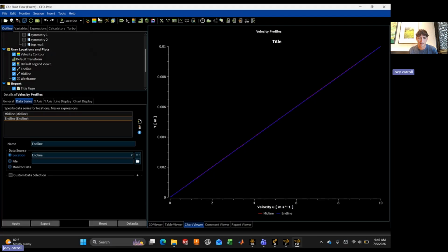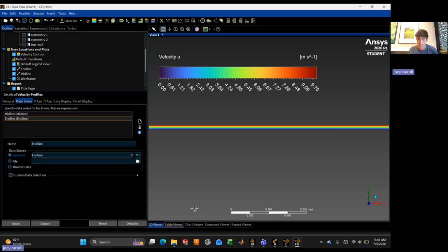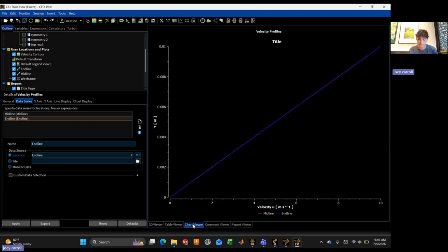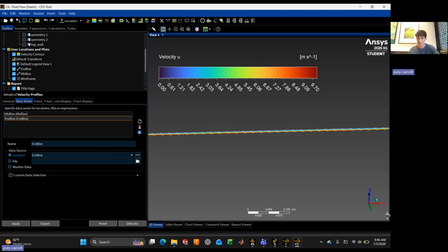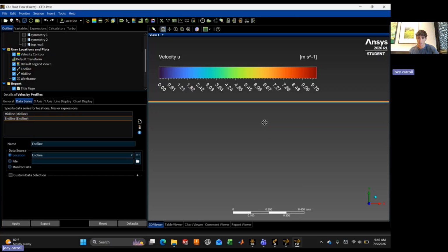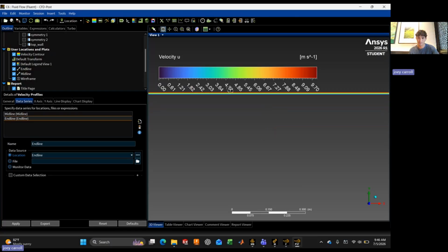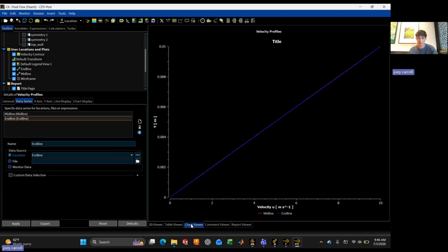Oops, my bad. So yeah, you don't navigate, you create things up here. Navigation's kind of down here, so I can go table viewer if I was dealing with tables, and then 3D viewer will show my gradient or contour and chart views right here. Yeah, so that about sums it up. For this, you're going to want to do the screenshot like I showed you guys. If you ever rotate, you press normal to the z-axis here. You can press control, and then move things up. It's going to take your snipping tool in. For chart viewer, you can also do your screenshots with this, and like I said, change it around.